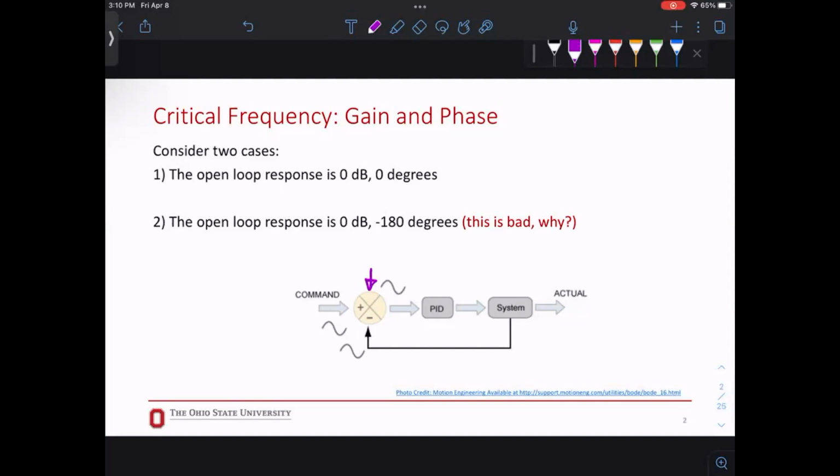So if you are at 0 dB and 0 phase shift, we are going to be marginally stable. So you're in a stable area. But if we go beyond that, if our phase shift is negative 180, that is the worst case scenario. Now, between 0 and negative 180, we want to see how much room we have to wiggle. All right. I think someone asked, Adrian, what are phase margin and gain margin when you're looking at a Bode plot, to solve the class participation, right?